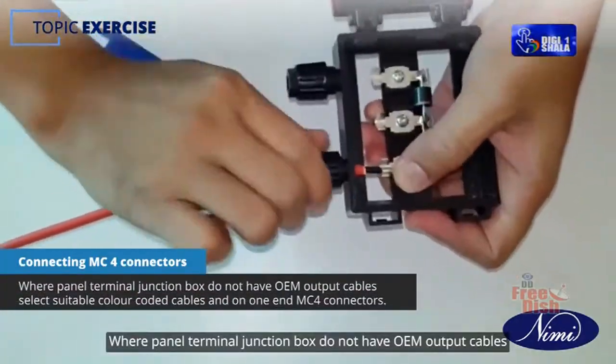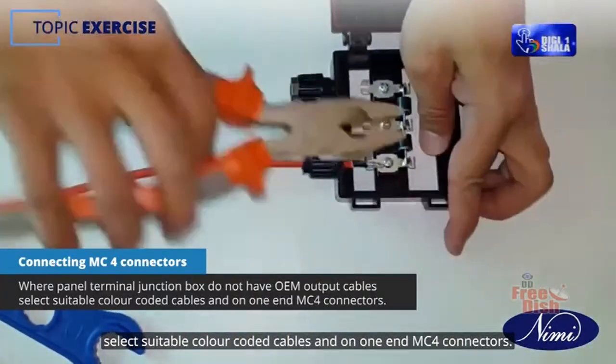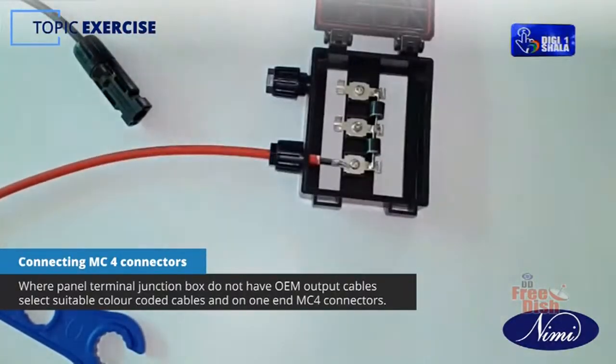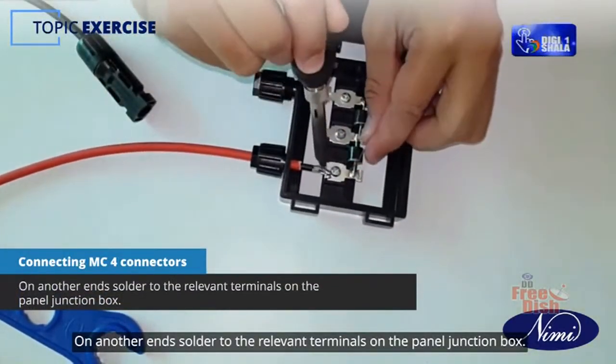Where panel terminal junction box do not have OEM output cables, select suitable color-coded cables and on one end attach MC4 connectors. On another end, solder to the relevant terminals on the panel junction box.